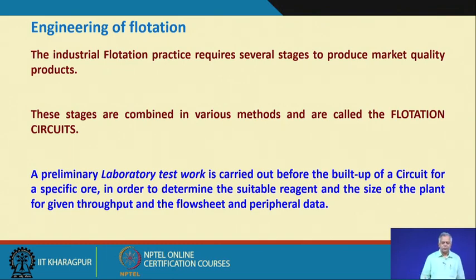It is analogous to what we do in the comminution process. Like I want to break the entire material to below 40 micron, the ROM ore. I do not charge the entire material to a grinding mill. I first crush it, and that crushing is also at different stages, and then we finally try to do it in a grinding mill. It is also the same thing, that you first remove some of the materials, and then you further improve the quality of your product in stages.